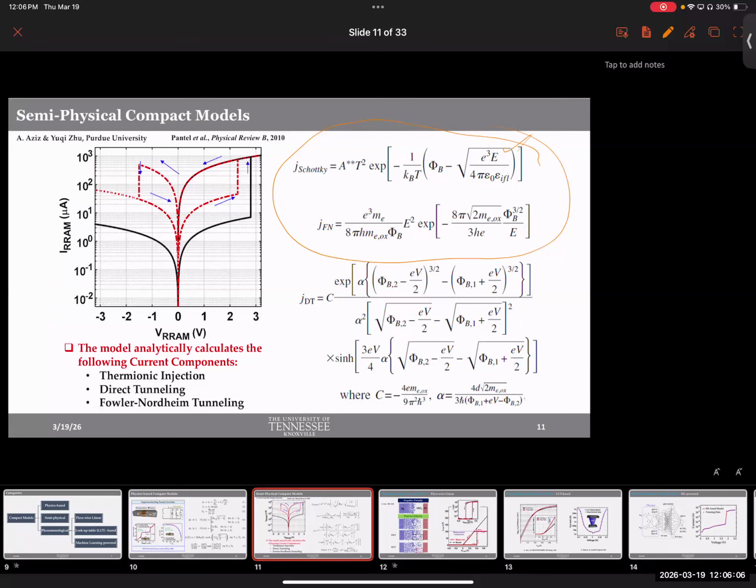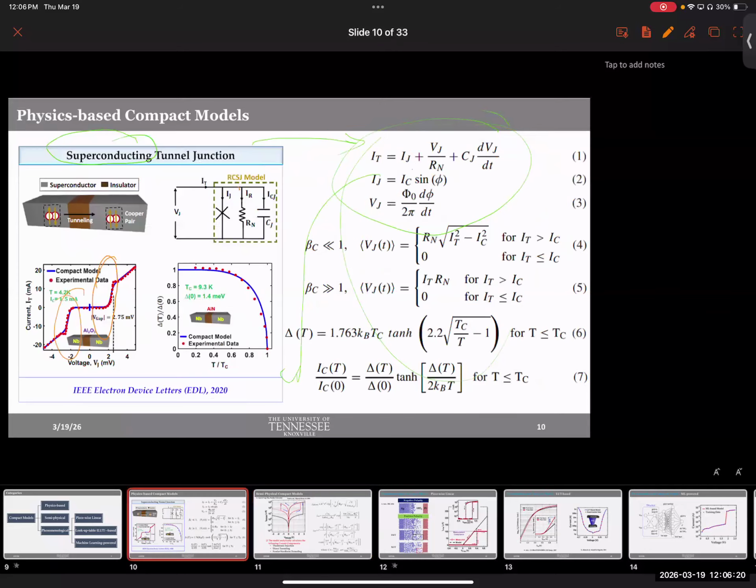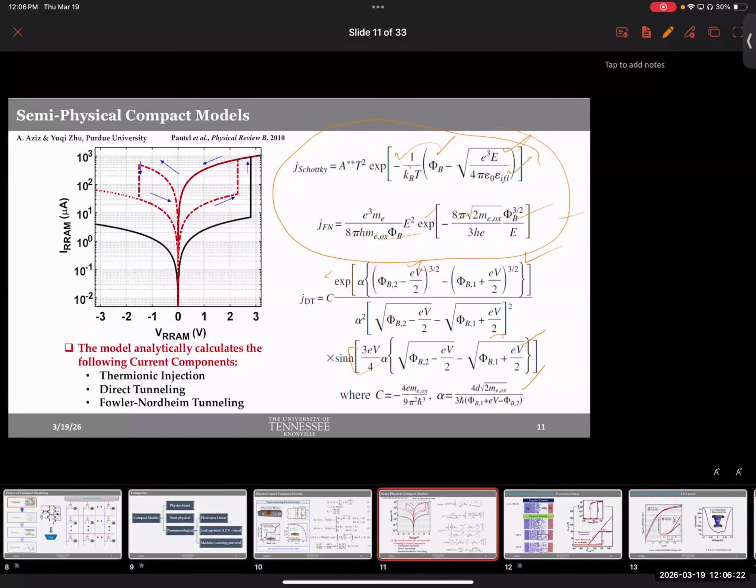Imagine how many parameters you'll have to define. You see that? Easily. And here, how many parameters? Many parameters, of course. And then you have to be mindful of the ranges of every parameter. Some of these parameters will be available in constants.vams, like kT, for example, the Boltzmann constant, pi. See? So you need all of this. What I'm telling you, these are definitely used in actual modeling. But the power is you can use this equation, copy paste it there, and then make sure all the parameters are accounted for accordingly. So that's what makes it very powerful.